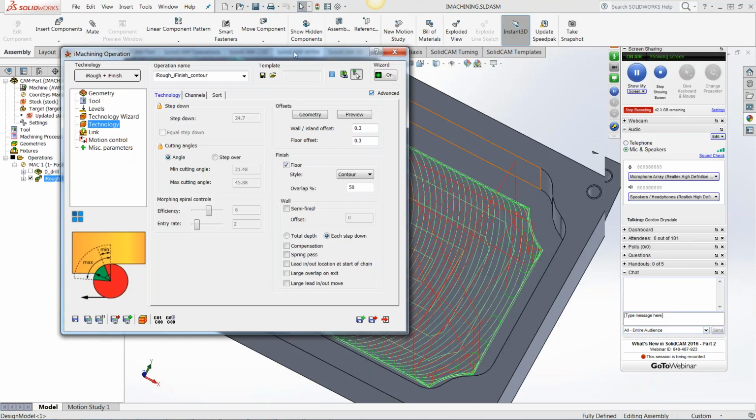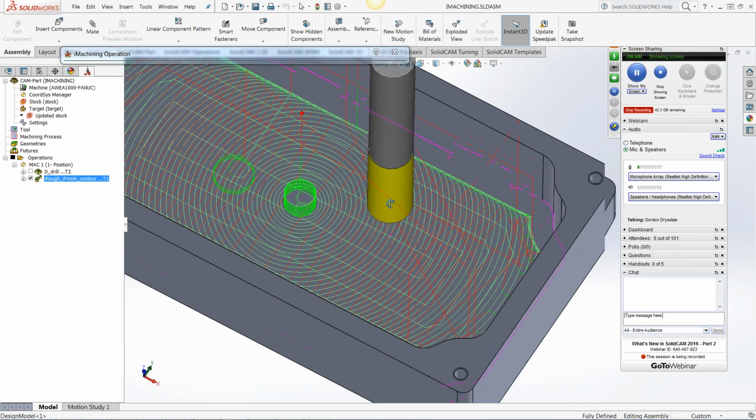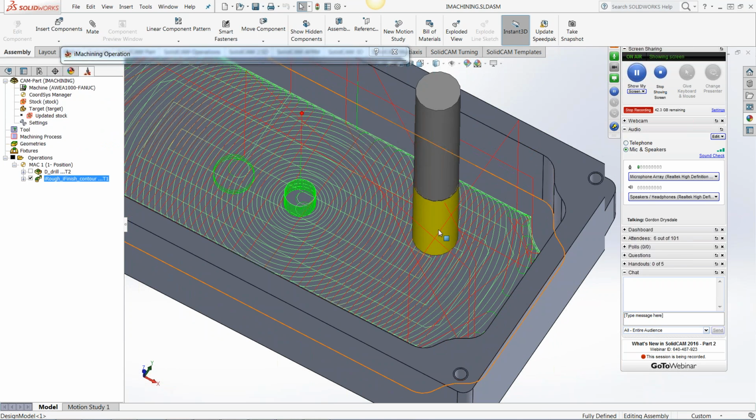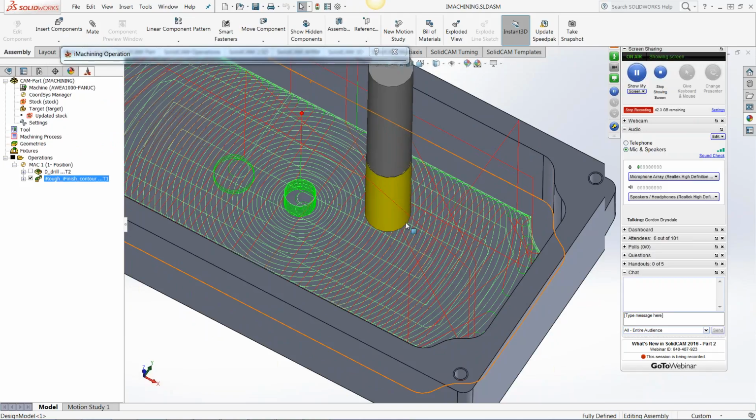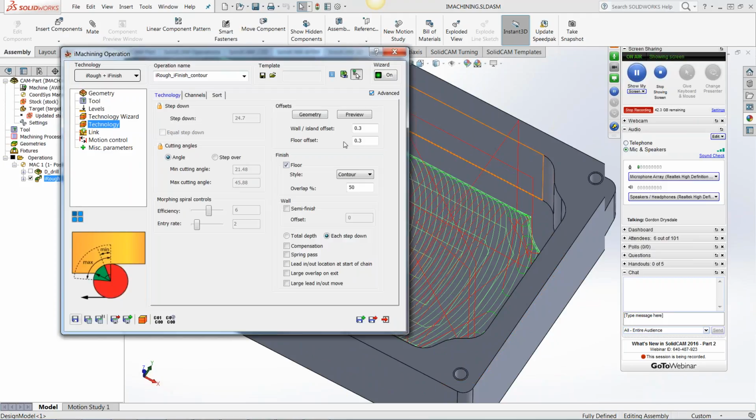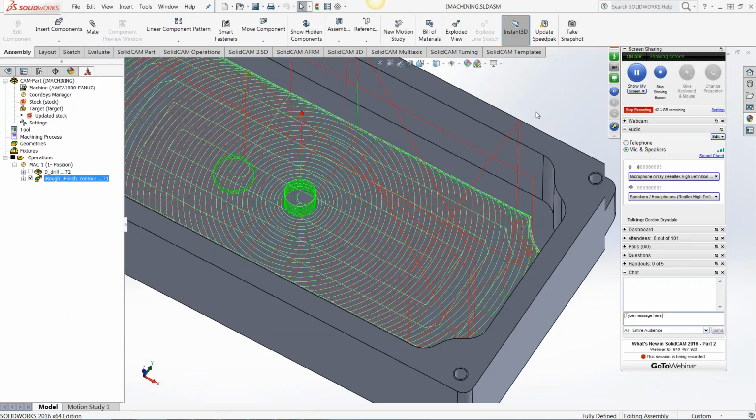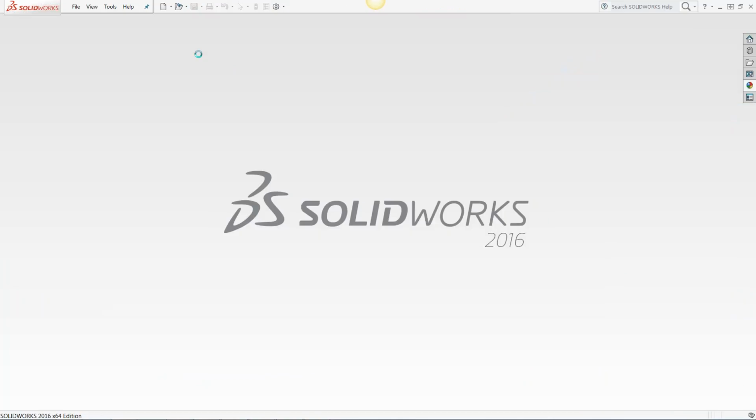You can see underneath the roughing toolpath where you've got the spiral moves, you can see the traditional step over of your contouring toolpath that you would normally get if you were machining any standard pocket. So you can choose the finish type that you may want to achieve on the bottom of a pocket now.